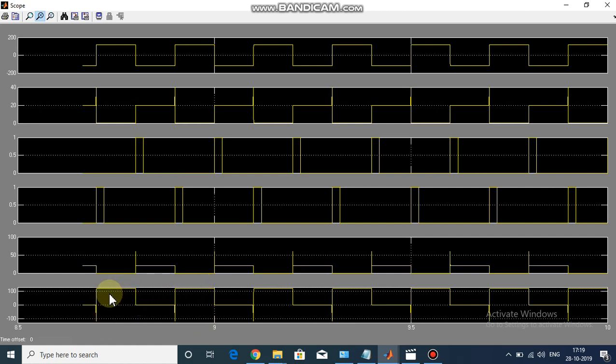If you just drag a line from here to here, see when the SCR is off there is no current, and when the SCR is on there is a lot of current. When the SCR is being turned off, like at this point of time, there is this negative voltage of the capacitor, around -120 volts, appearing across the anode cathode region of the SCR, which is why there is the turning off mechanism of the SCR. So this is pretty much the analysis of the waveform.